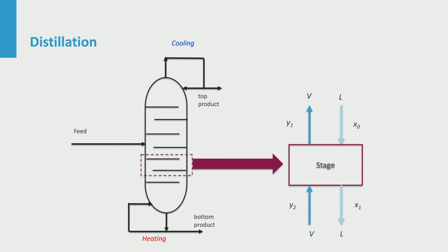In distillation, the bottom is heated and the top is cooled, leading to a desired temperature gradient and high energy costs, of course. Liquid flows down and is heated by upflowing vapor, which is cooled in this way. In each stage, liquid components evaporate and vapor components condense, depending on their local volatility, which is hard to predict for many biotech mixtures because of hydrogen bonding. In favorable cases, the local equilibrium of the countercurrent flows leads to very good separations.